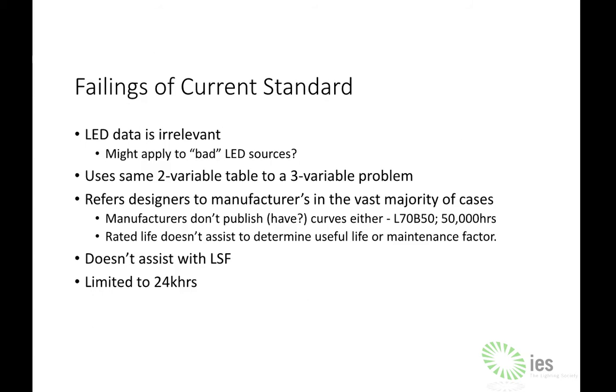And certainly that table didn't help with LSF. It just said 1 in all cases, and then it got to a point where it said, talk to the manufacturer. And that's actually an F value. That's a whole different thing, and I haven't even addressed that. So if I haven't addressed it and the standard hasn't addressed it, we're all still in the dark. And that standard was, of course, obviously limited only 24,000 hours, and I haven't seen many LEDs published at less than 30,000 hours.